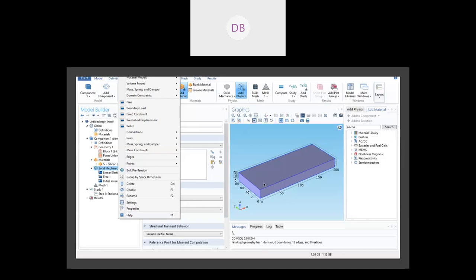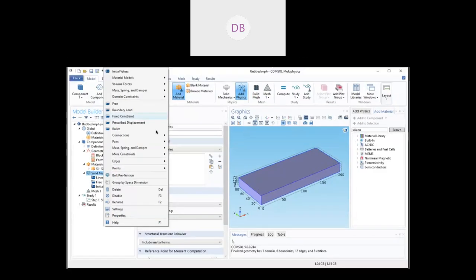So here, all those parameters, that is, we want to make the fixed end, we want to create the loading end and everything. So next step, as I told you, we select the fixed constraint, that is, which end we want to fix. You can see the XYZ parameter is shown over here on the console. The XYZ parameter, you can select. You can change the direction also. It is not an issue. We are taking from the 0 0 orientation. You can go in the minus x, minus y, minus z direction also, or you can go anyhow. This is drawn in the positive axis, positive x, y, z.